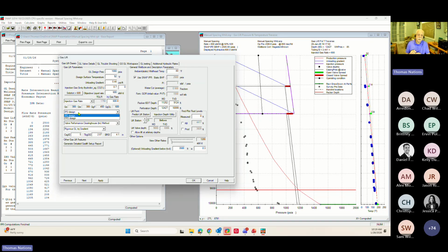So that's injection pressure operated. Production pressure operated would be changing where those pressures act. The injection gas pressure would act under the trim of the valve, under the ball and seat, and the flowing tubing pressure would be rerouted to act on the outside of the bellows.